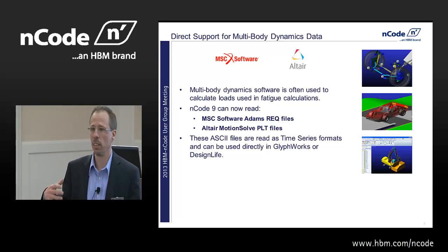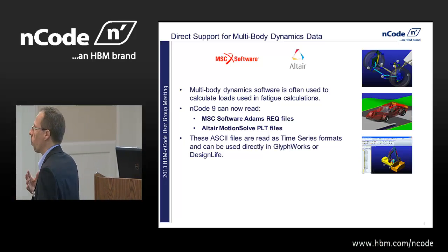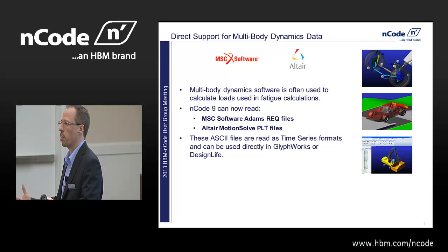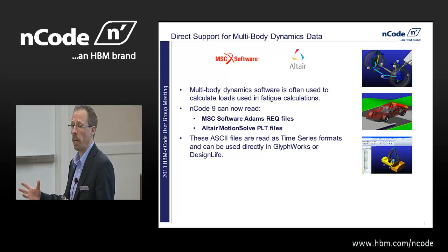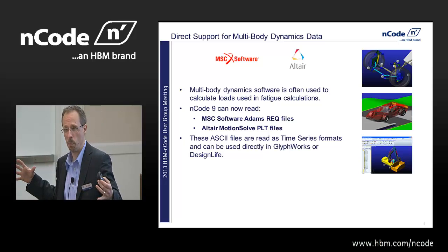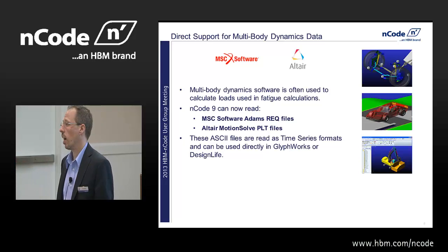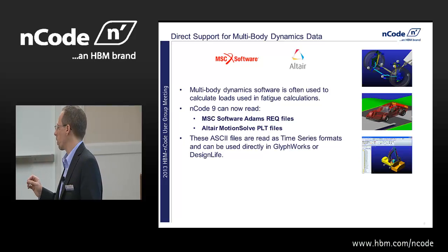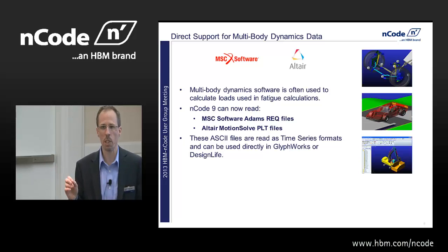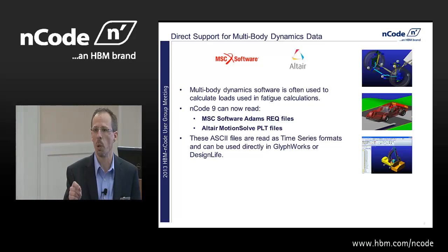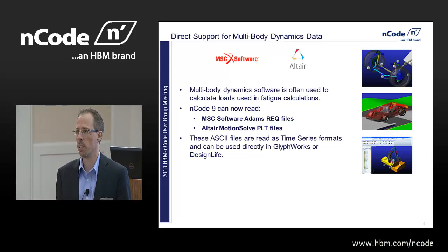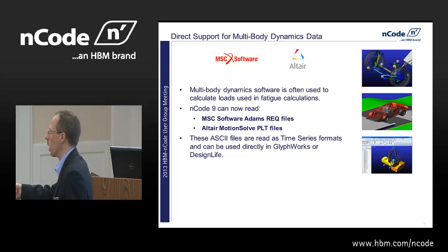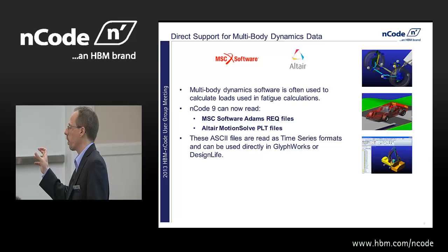It's solving what loads are going into a kinematic system, and then calculating forces and displacements at various points in this computer simulation. And this can be really helpful for durability, because I don't know if you've noticed, but it can be really hard to measure exactly what you want to measure. It's really hard to get the strain gauge right where you want it. It's really hard to get your load cell on exactly the component that you want to get the loads on.